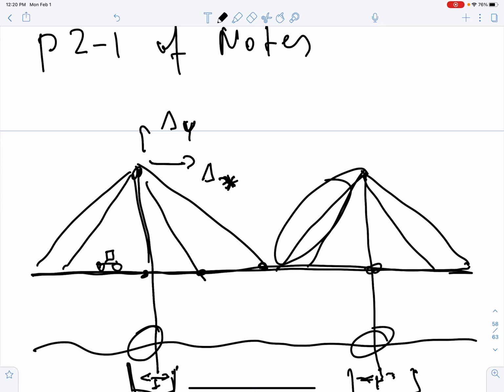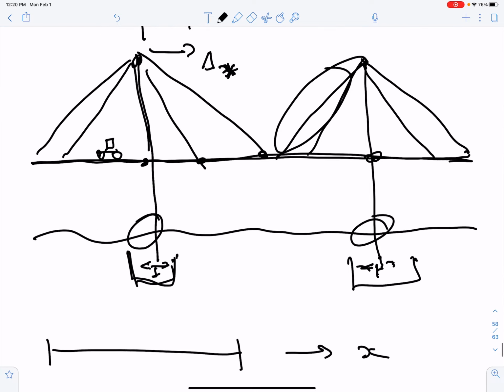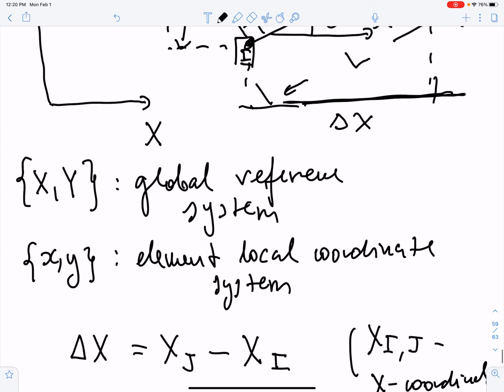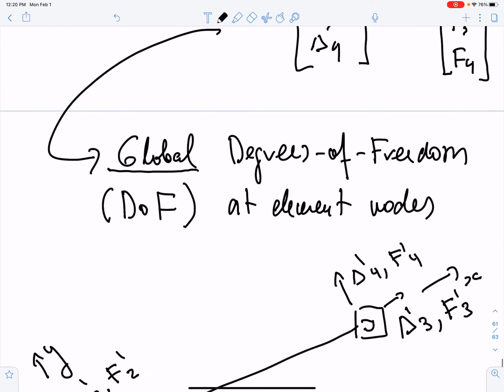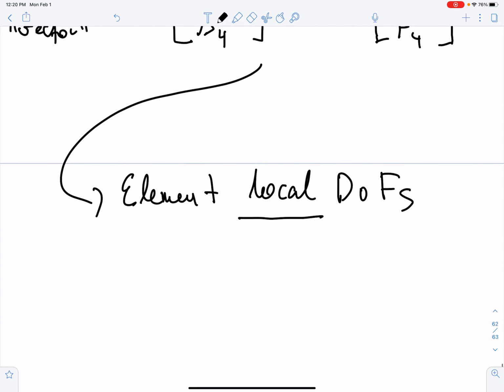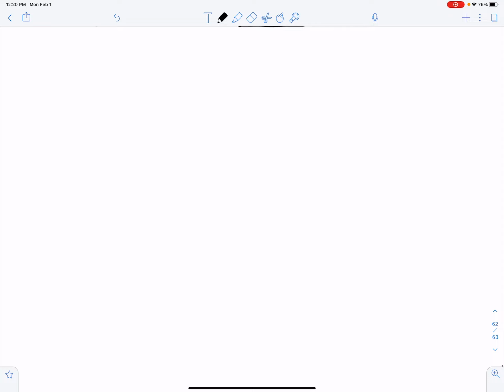because that's not where your differential equation lives. Your differential equation lives in the axial direction. So for that one, you need a local coordinate system. And so as you've guessed by now, somehow you need to do some operations at the local level, and then you need to bring things to the structure level. At the local level, things will live in a local coordinate system. At the structure level, things will live in a global coordinate system. So then you need to relate them.